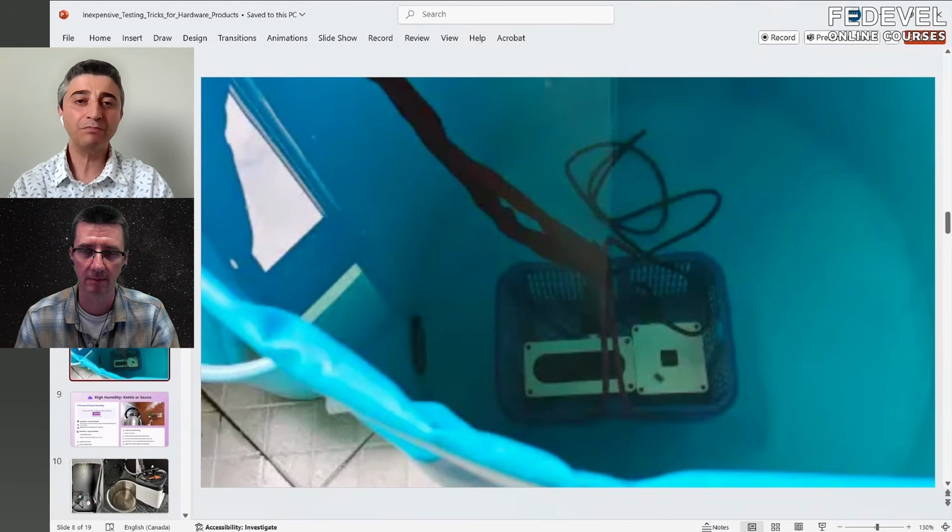So you can build that thing easily, with a tank, a fan or a blower, a vacuum, and then you can put your device inside, and you can collect dust anywhere you like from your environment. That way you can blow the dust around your product and find if there are issues for your sensors, for your sealing, if there's anything that might get into your ports, like a USB port or an Ethernet port. If you have the right sealing in place, you can find this out easily.